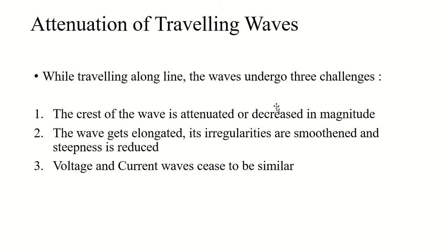And why do these losses occur in the system? Because of the line resistance, leakage conductance, corona, all such causes. So the losses due to the line resistance are very important. Losses due to corona at high voltages are greater than the losses generated from the line resistance.